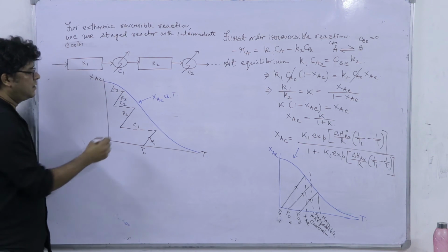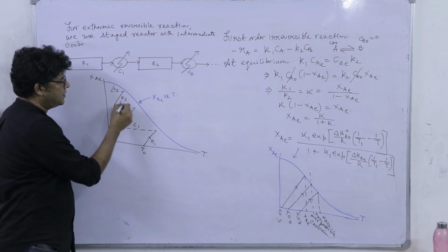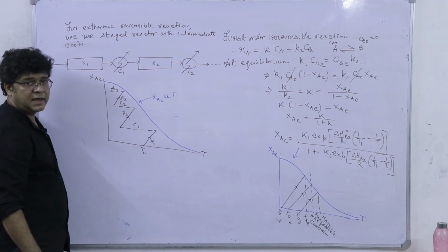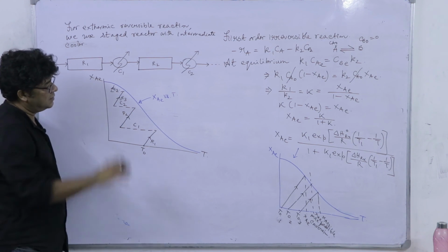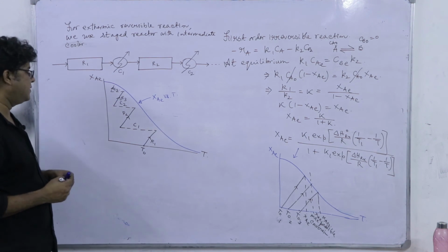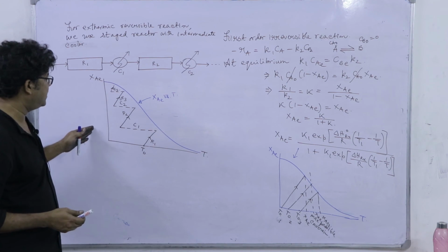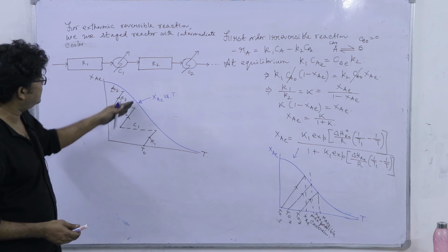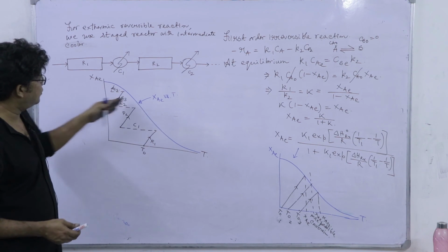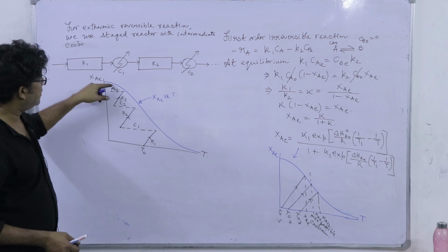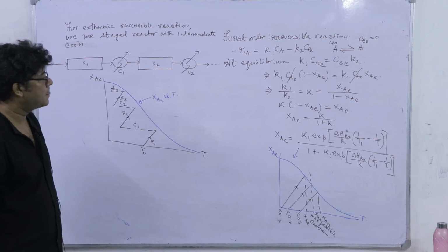So we can reach a very high conversion even for this exothermic reversible reaction, where my final outlet, instead of using a low temperature feed, even if it is possible with the lowest temperature feed, still you can go here, but if you use intermediate coolers, you can do this and you can go for a very high conversion, right.